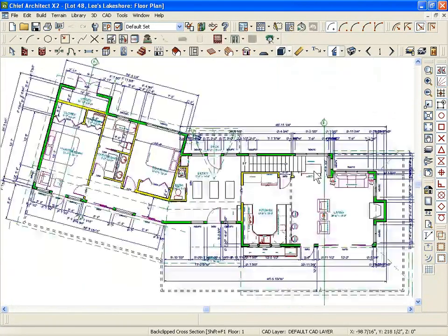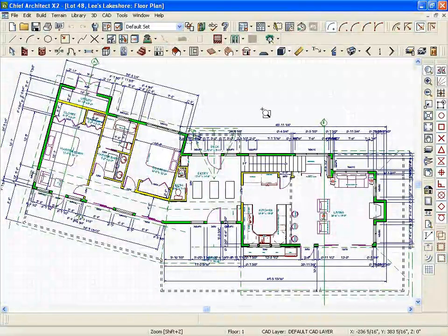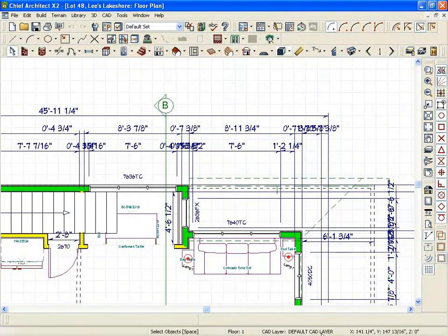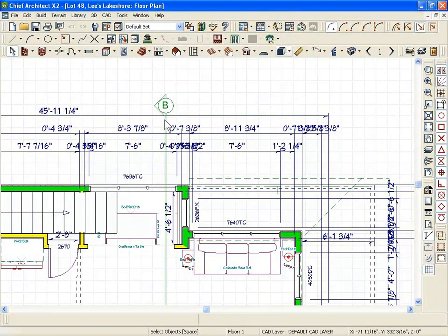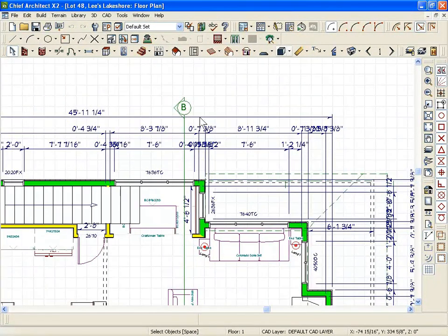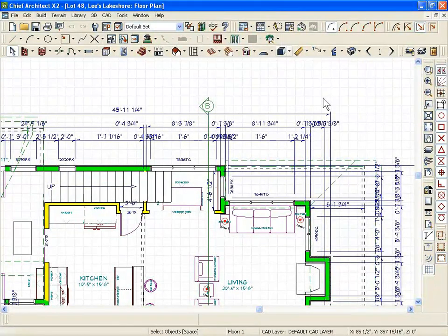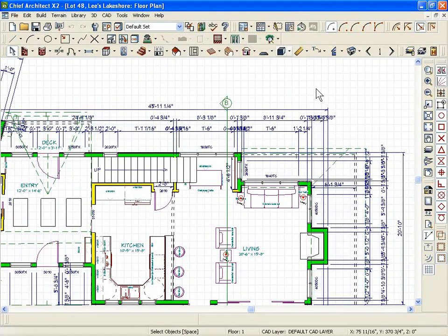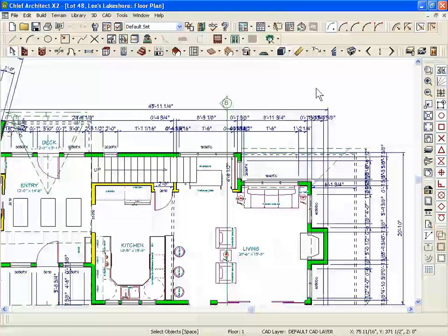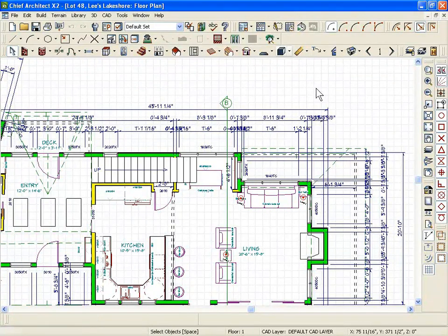On this plan here, if we take a look at what I had to work with when I got the plan, dimensions were set up wrong, lots of fractions everywhere. I had to go around the whole plan and spend time cleaning it up. Not a big deal, but if that were done as it was laid out, it would have saved the trouble of having to do that later. So watch that as you're working on your plan. Get those dimensions in the right place.